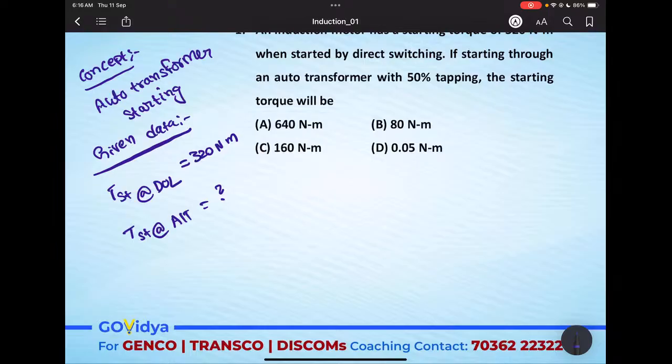The full load torque is directly proportional to the rotor input, the rotor mechanical input, that will be 3 I square full load R2 dash divided by SFL.